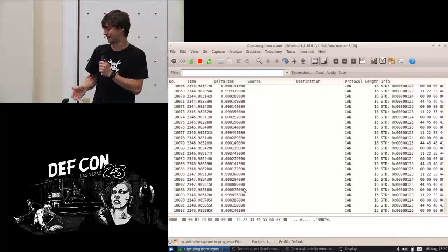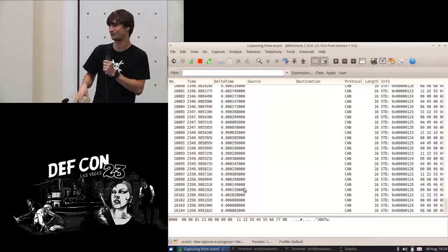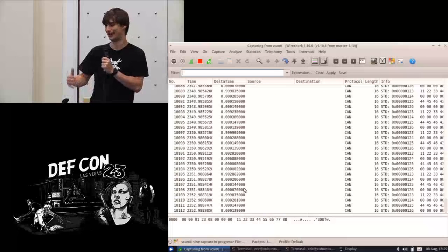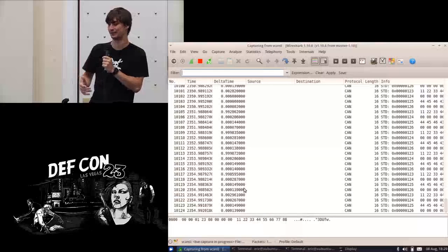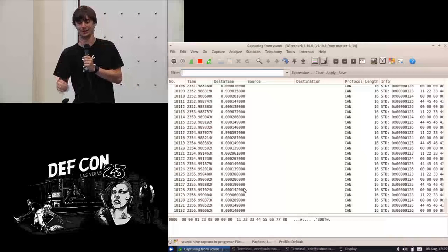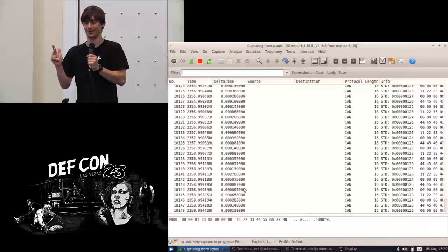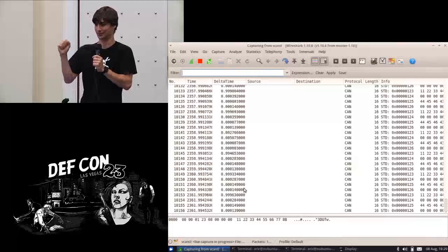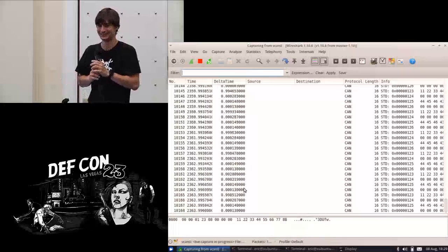So one thing I'm working on are some new open source software tools for doing the higher level protocols, but SocketCAN itself is very raw. It's, give it 8 bytes, a data length code, and an ID, and a message ID, and it will send a frame. That's about it.